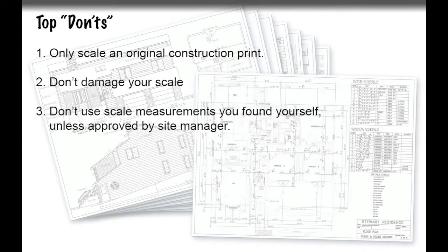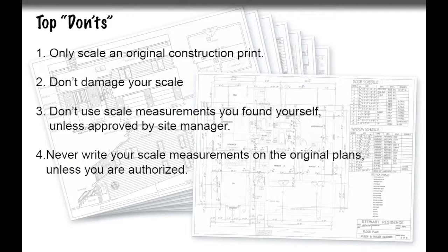3, don't use scale measurements you found yourself unless they are approved by the site manager. And 4, never write your scaled measurements on the original approved set of plans unless you are authorized. Ask for a markup copy to be written on. Have the site manager approve your scale before they are used on the job.